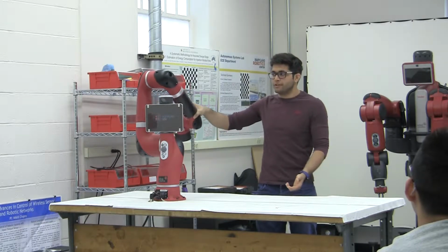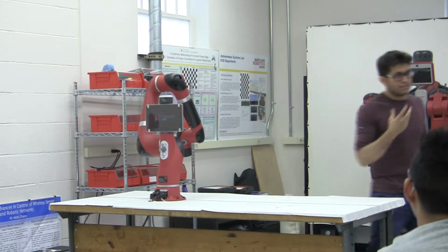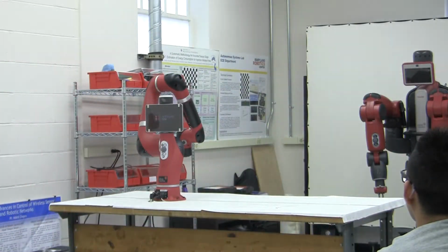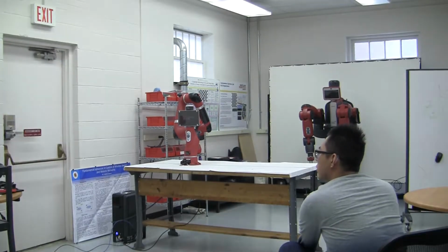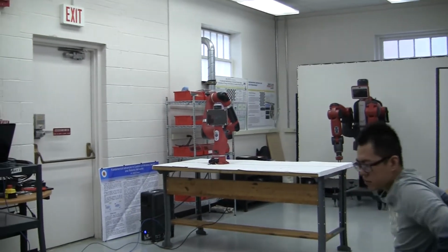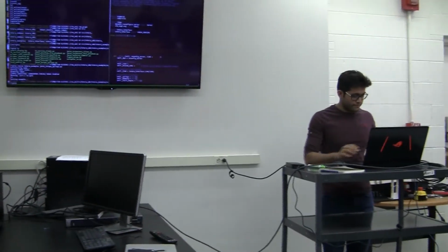For each joint you will figure out it can't go there, because each joint has a fixed amount of collision space defined in the URDF, and the robot now reads from that URDF and agrees that that's our collision space and we can't do that. So that's how it works, but let's go through the script itself.